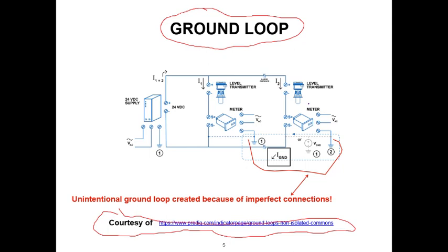The trouble is they can be very difficult to diagnose and troubleshoot because the problem will generally be intermittent. So a piece of machinery or equipment or a controller may occasionally act kind of flaky or weird, but not all the time. Definitely, I would suspect a grounding problem. So it's something you want to try to minimize, hopefully eliminate, during the initial installation.